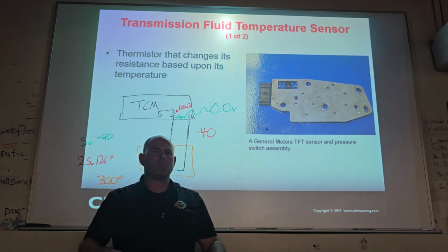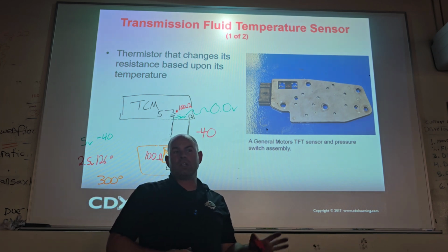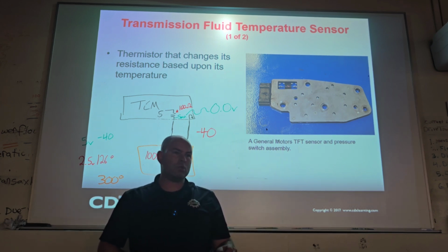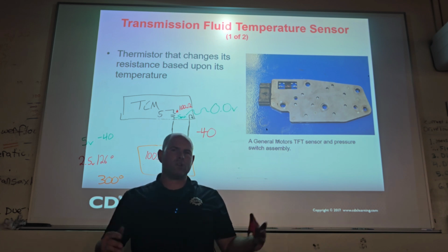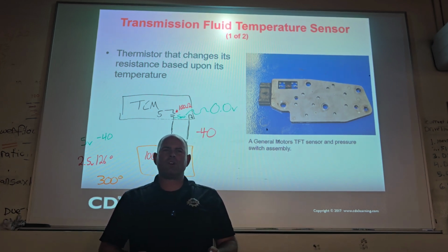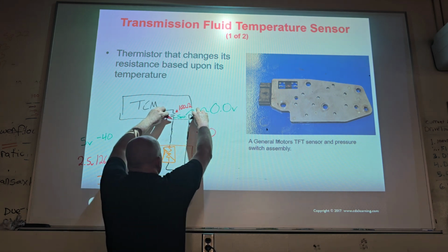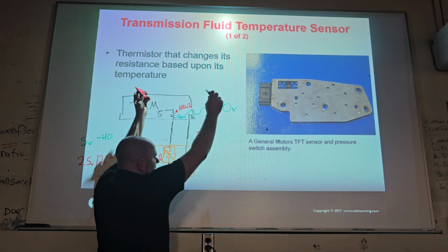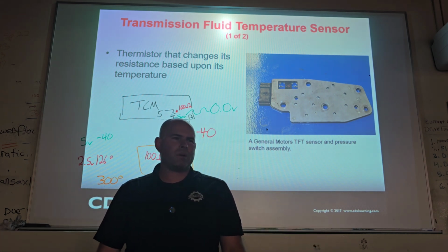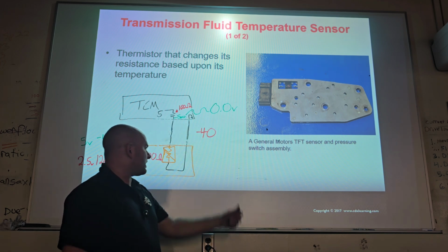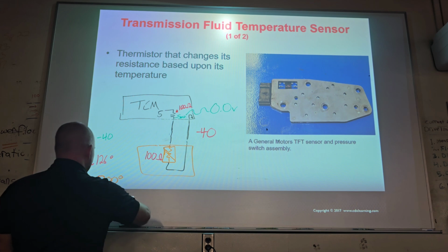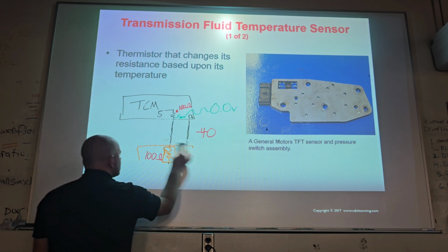The engineers tend to be really heavy on whether it's shorted to voltage or shorted to ground. Most of the time, you know what it is? It's chewed, it's cut, it's a loose terminal, it's corroded. The shorts can happen, but if I first checked and it was OL, well, in fact, if it was shorted, it wouldn't even be OL. So if it's OL, I'm not real nervous about it. See what I'm saying? It's kind of weird, but that's how I would keep it simple, stupid. That's how you diagnose any temperature sensor. Cool? Now, we must continue on.